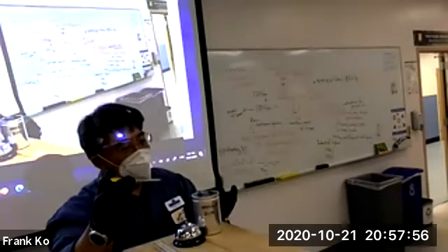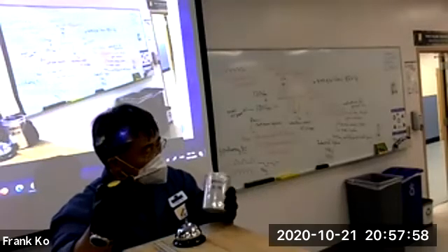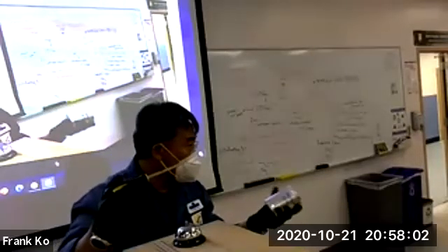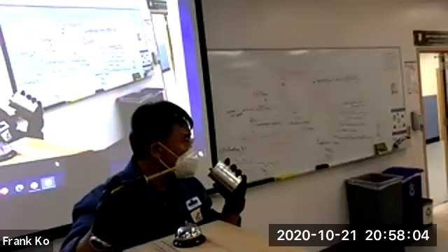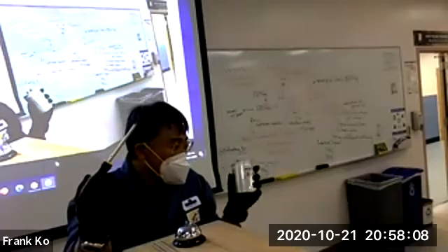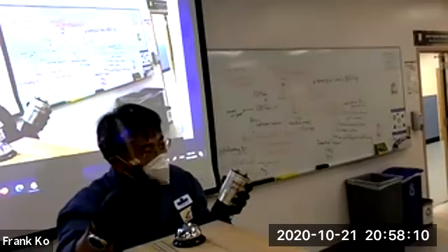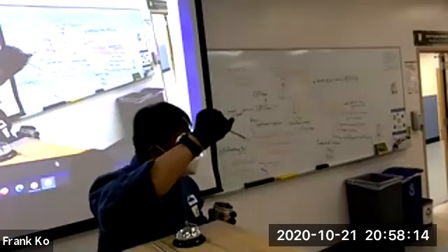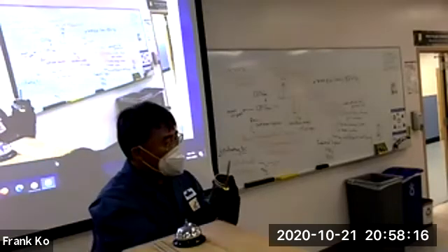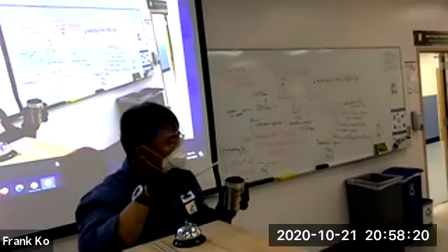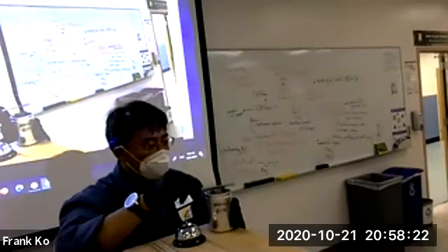So in a work situation, technicians who encounter large capacitors don't know if it's charged or not. You're not going to do a tongue test like you would a 9-volt battery, right? You're not going to do that. So you're going to use a special probe that has a large what inside the handle? Resistor in the handle. Attach the ground wire to the ground terminal, attach the probe to the positive, and it will discharge safely. This was not a safe discharge.